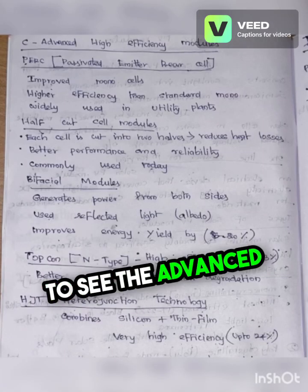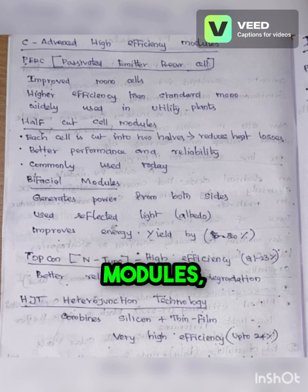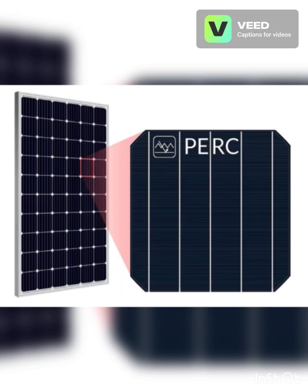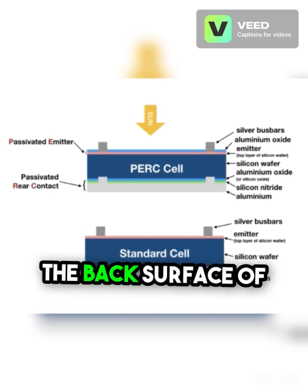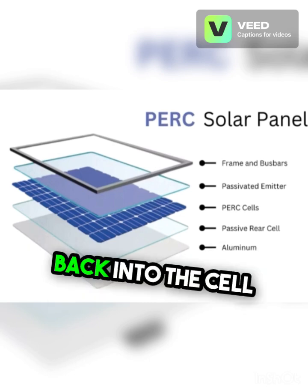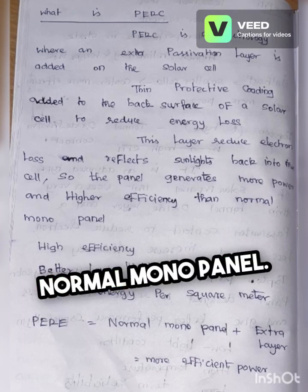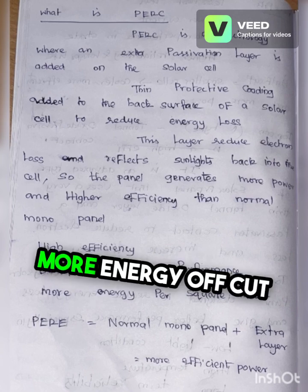Next we are going to see the advanced high efficiency models like PERC, half cut cell models, bifacial models, TOPCon, HJT models. First, what is PERC? PERC is a technology where an extra passivation layer is added on the solar cell. It is a thin protective coating added to the back surface of the solar cell to reduce energy loss. This layer reduces electron loss and reflects sunlight back into the cell, so the panel generates more power and higher efficiency than a normal mono panel. This is PERC: high efficiency, better low light performance, more energy.